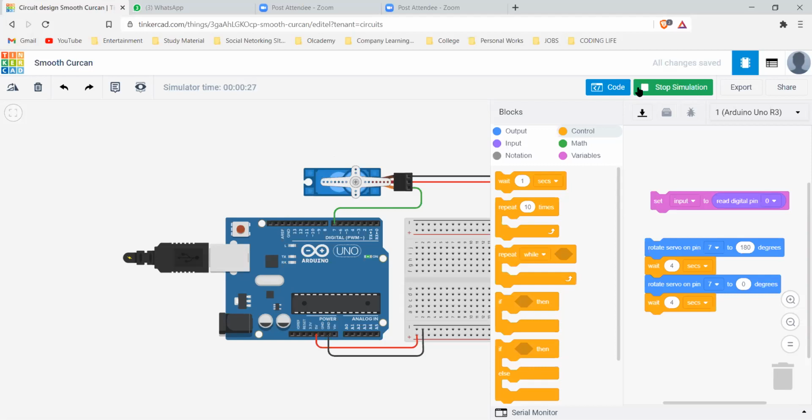What you have to do is you just have to give output to a certain pin. That pin will take the output. You have to wait, then change the output. So digital pin's output can be changed from 0 to 1 back to 0. So this is how you signal.